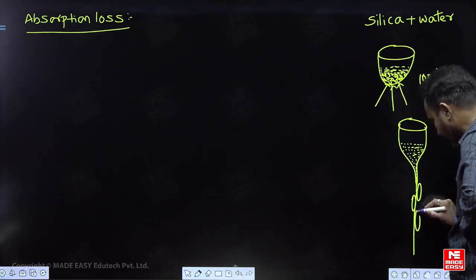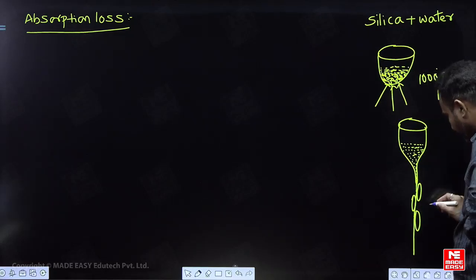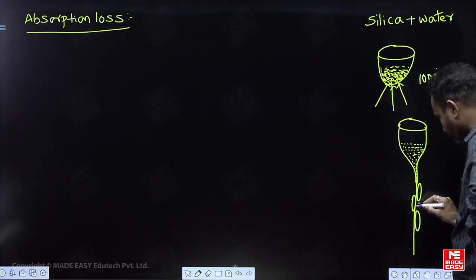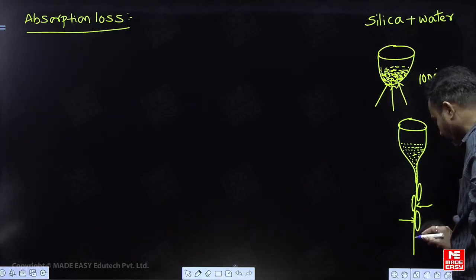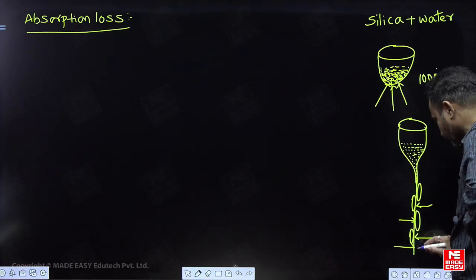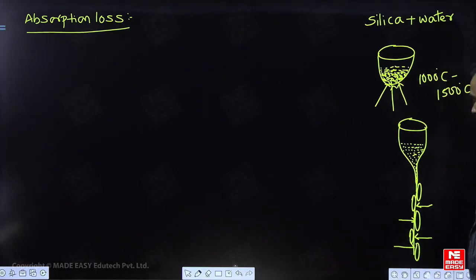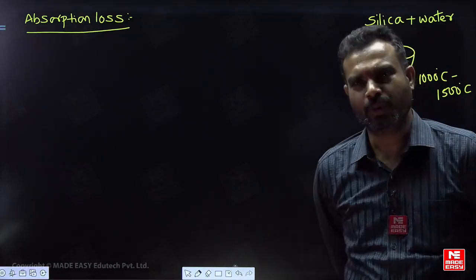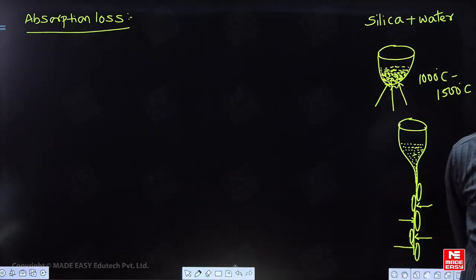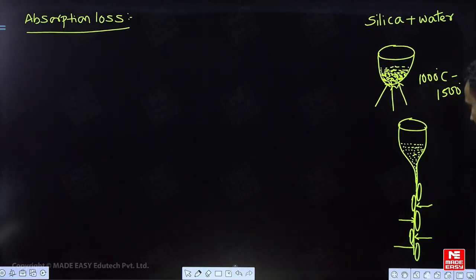The fiber is rolled from the molten liquid, and you are doping some of the impurities. By doping the impurities, we form the clad. By rolling, the fiber is formed with a length of 10 kilometers or 20 kilometers, and of course higher lengths are also possible, but we can restrict the fiber to up to 20 kilometers of length. Like this, 20 kilometers of fiber can be manufactured.